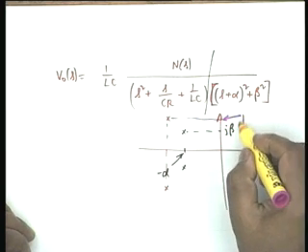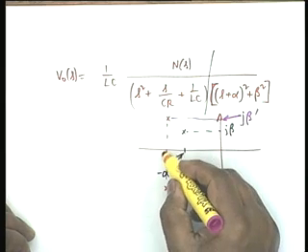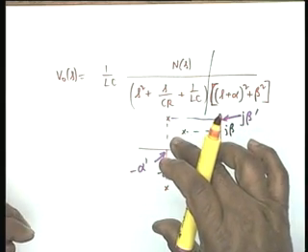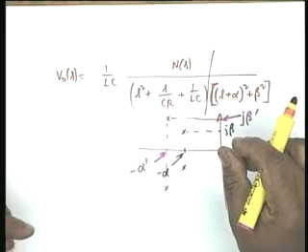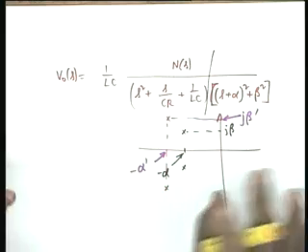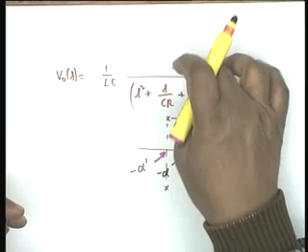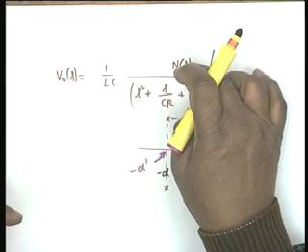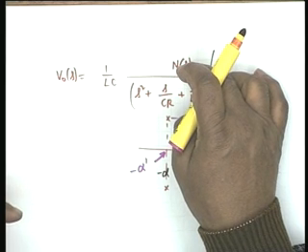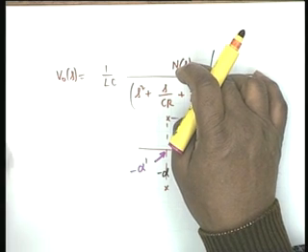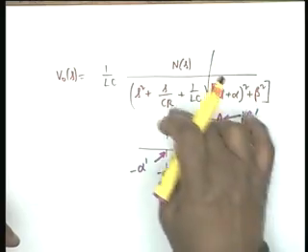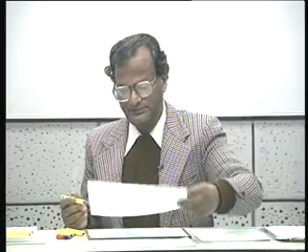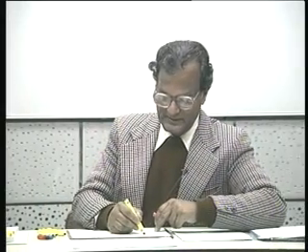Suppose this is j beta prime and this point is minus alpha prime. This is a perfectly legitimate location of the poles. There are 4 poles. Are there any more? No, because N of s is of degree 3. If the degree was 5, let us say, then there would have been a pole at infinity. It is of degree 3. So, these are the only locations of poles, and I can now write down V0 of s.